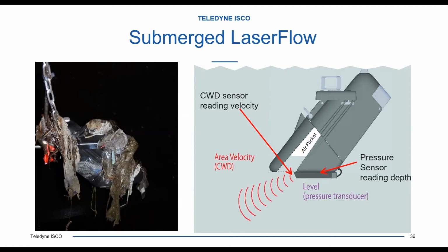Now, having said that, if it did happen to get splashing or something up in that window, the laser has what we call an optical clarity system. It detects backscatter of laser light coming into the laser. So if it fogged up, say I had it in the back of a truck and it's 20 degrees out and I put it in a manhole, it could fog up like your glasses. Also, if it did submerge and you got splashing, that could cause you potentially some issues. So we came out with the optical clarity system, and now it will turn on a small window heater, warm the glass, and problem solved.